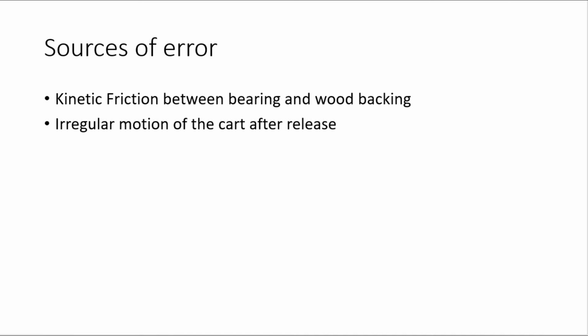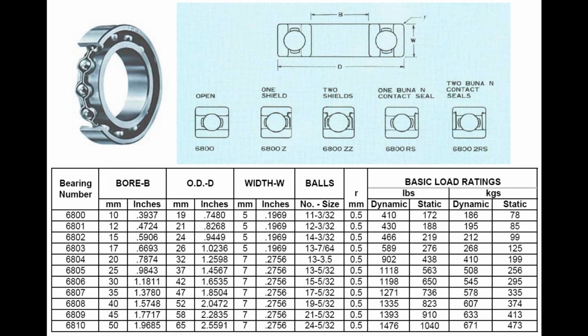We expect there are two main sources of this loss: the kinetic friction between the wheels and the ground, and the poor design of the release mechanism. Ball bearings are only considered frictionless when under a sufficiently large load. We expect the weight of the cart to be inadequate for this, and ultimately lead to more sliding than rotation of the bearings. To minimize this in future experiments, we could have degreased the bearings to lower the rolling resistance, or added more weight to the release mechanism.